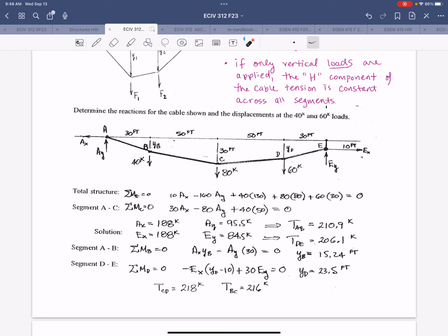All right, so here, this is a photo I took of a truss in a local establishment. I wouldn't expect anybody to recognize it and know what establishment it is. It was a cafe. And here you can see this is a roof truss, or it's supporting the roof. You've got top and bottom chords that are steel I-beams, and then the web members consist of, the vertical ones are these wood posts, and the diagonals are ties, right?